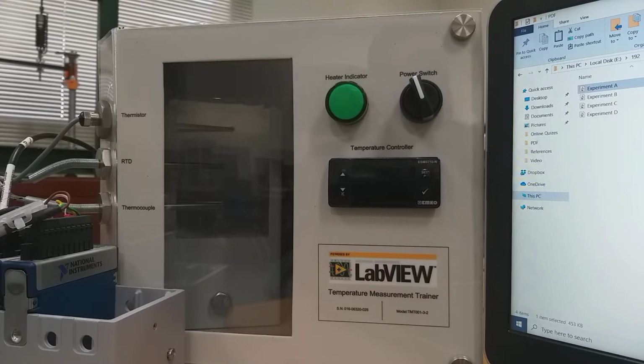The experiment title is Assessment of the Performance of Different Temperature Measuring Sensors. The objectives of this experiment are to assess the thermal response of three different temperature sensors, which are the thermocouple, RTD, and thermistor. This will be achieved by comparing the temperature readings of these three devices with the reference value. Also, we need to check for hysteresis error in the sensors by measuring different temperature levels during heating and cooling. And finally, we need to check the validity of the equations that are given in the manual.